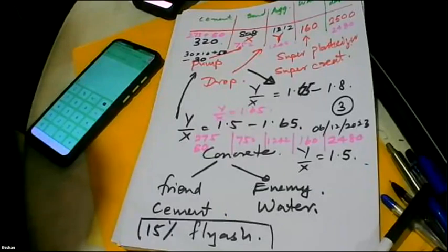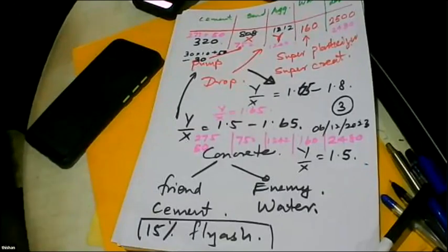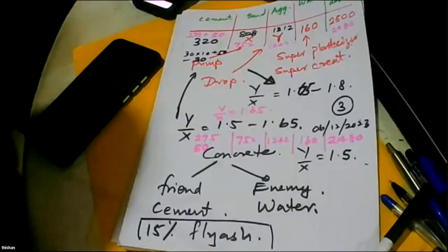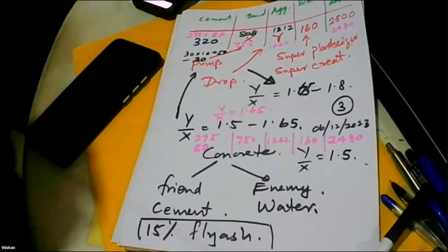No. Whether you are designing with 30 megapascal or 40 megapascal is important only when you are designing as a beam. Even as a beam, if you have a 3 meter thick raft, would it matter? No, it won't. Whether you use 30 megapascal or 40 megapascal, the amount of reinforcement that you need will be exactly the same. So in such a scenario, is there any point in selecting 40 megapascal? No point. So don't select high strength concrete for the sake of selecting a high strength concrete.